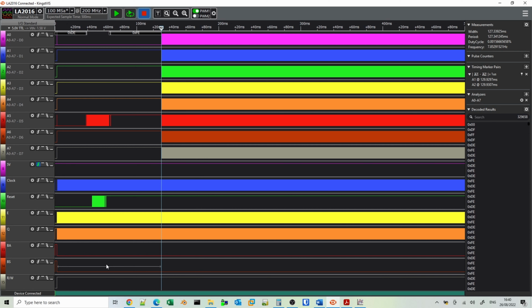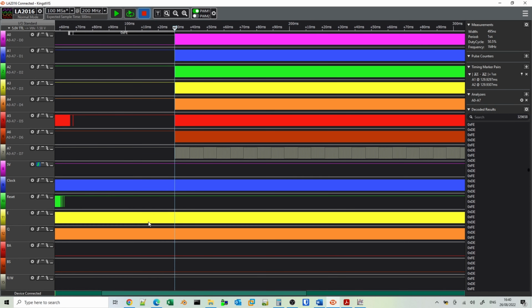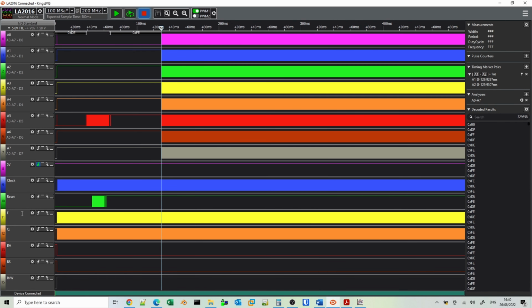So the reason for looking at this is to make sure we find what the right signals are that we're going to look at. And obviously going forward, we're only going to be using the E signal for determining the memory access clock. But should we want to use faster processors and have problems with accessing slower memory, then we might want to consider using the Q and the E clock to gain access to this.